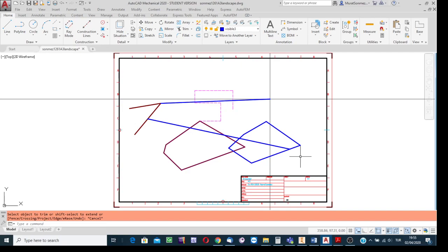So use the snap facility. And then in the last exercise I said that, well, the terminal point of the line is not at a characteristic location. How can it be ended precisely along a certain boundary? I said use the trim technique. Have further extension and then trim the unnecessary part. Okay.